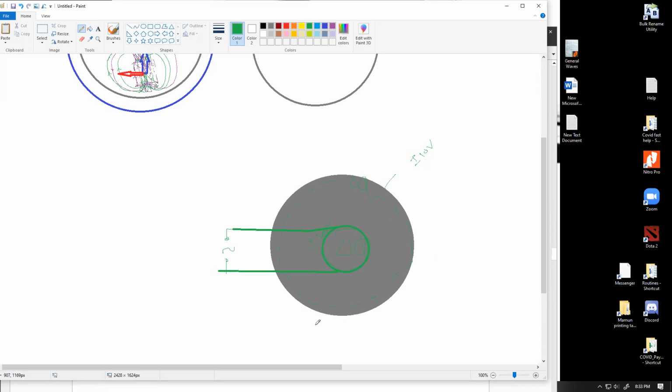Eddy current. In the reverse cycle, the center, let's say, becomes minus 200 volt, and the periphery becomes minus 10 volt. So in that case, the periphery is the high voltage and the center is the lower voltage. So in that half cycle, current will be traveling from the radius inward. So in all the directions, current will be traveling back and forth like this, concentrating and spreading, concentrating and spreading, concentrating and spreading, like that. That basically produces the heating.